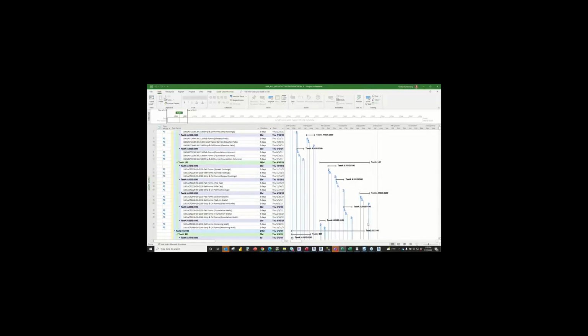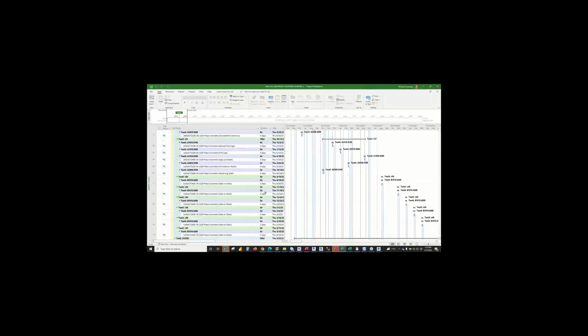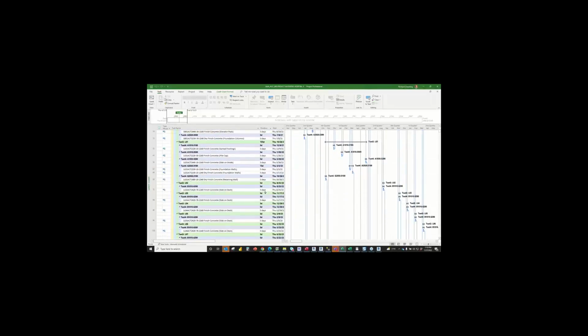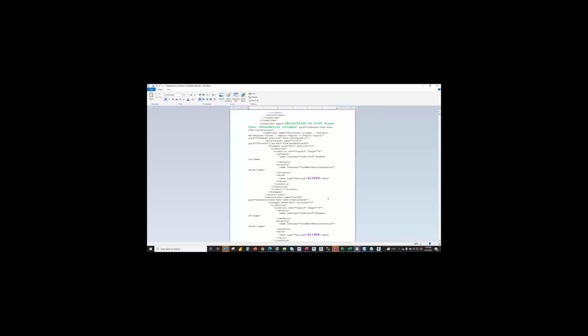I've provided my logic, really kept the durations the same for the sake of presentation. Now the silver bullet is that I've created XML selection set import files that I can import into Navisworks using a selection set naming that's consistent with the task or activity ID.